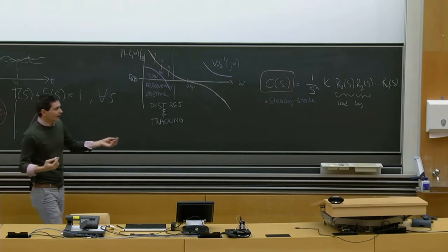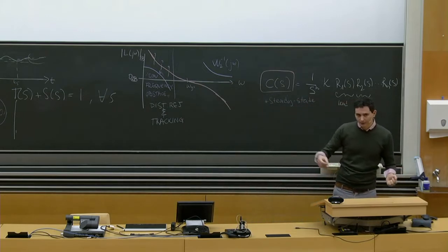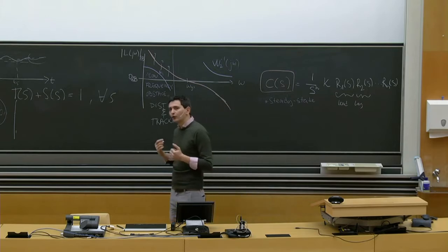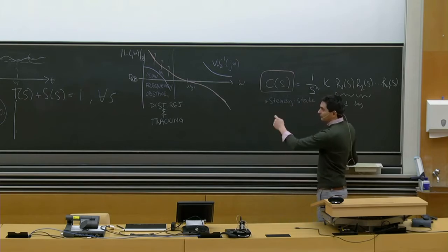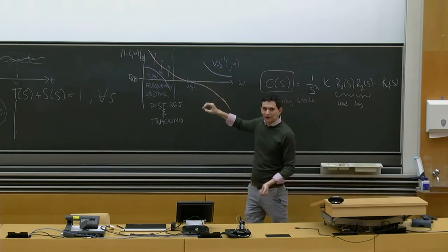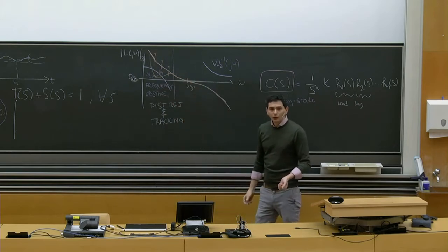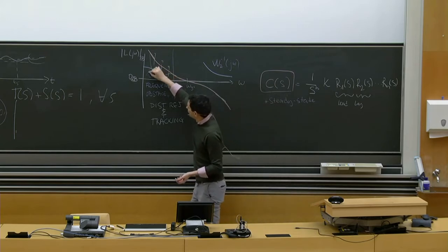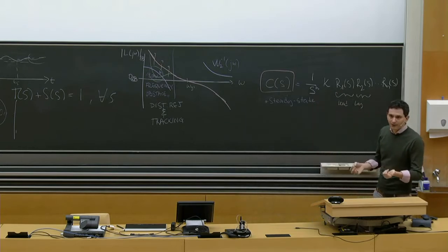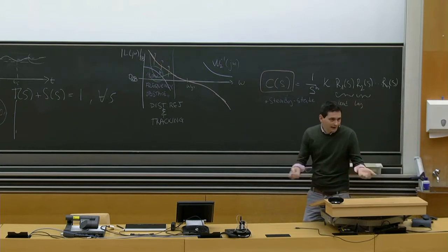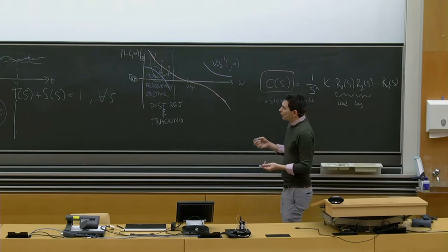So why does this make sense? Well, we saw that the lead and the lag elements, designed appropriately, we will see an example today, allow us to bend the L plot only locally at specific frequencies. Say that for some reason you've got a plant that is like this, okay? So you would like to make sure that this part does not collide with the low frequency obstacle, because that would mean not satisfying some specifications given for hopefully some good reasons by your boss. So what would you like to do?